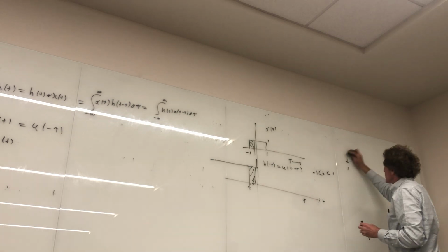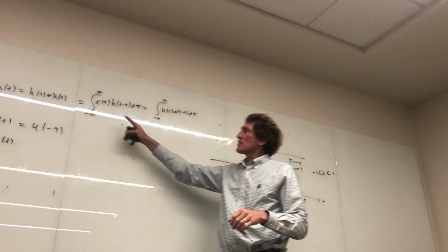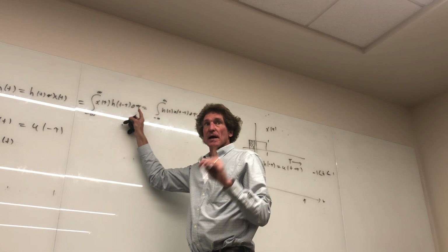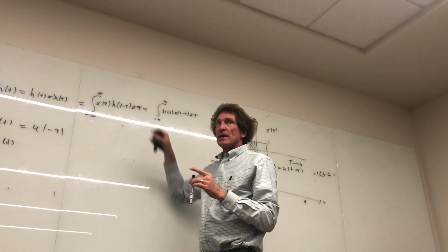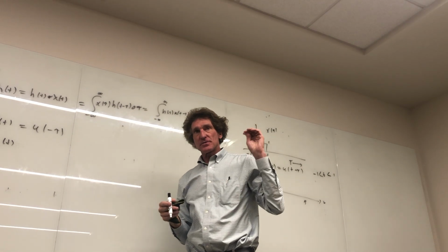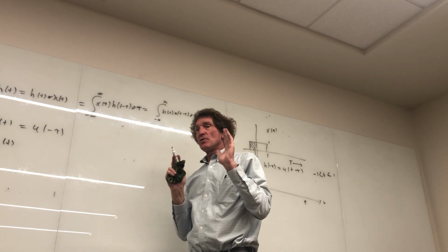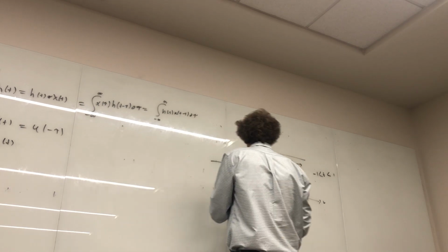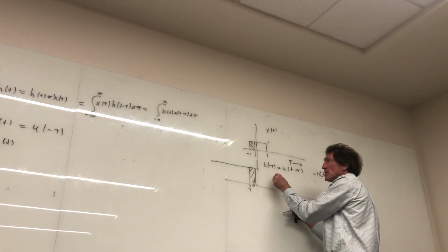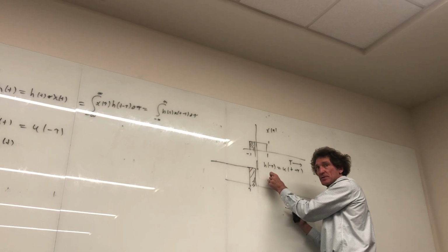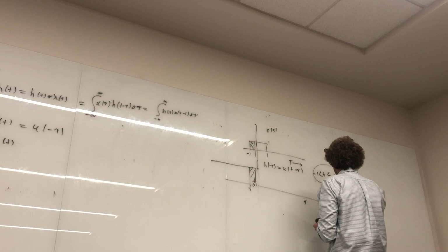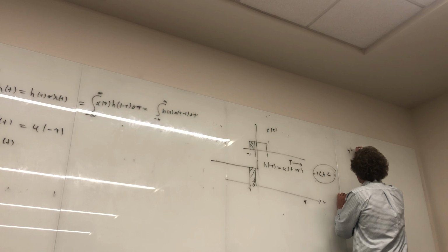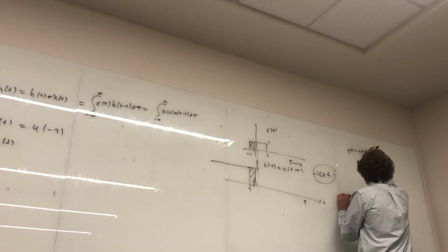Just take a look. Now, look what it says to do. It says to integrate these two functions, d tau, after they're multiplied together. Because our integration was with respect to tau, this gets a little confusing, but what you have to do is look at the different points in time where there will be different areas of overlap. Between here and here, we're just drawing the curtain, so it's pretty clear how to write that expression. We can say the convolution of the two, y of t equals x of t convolved with h of t.